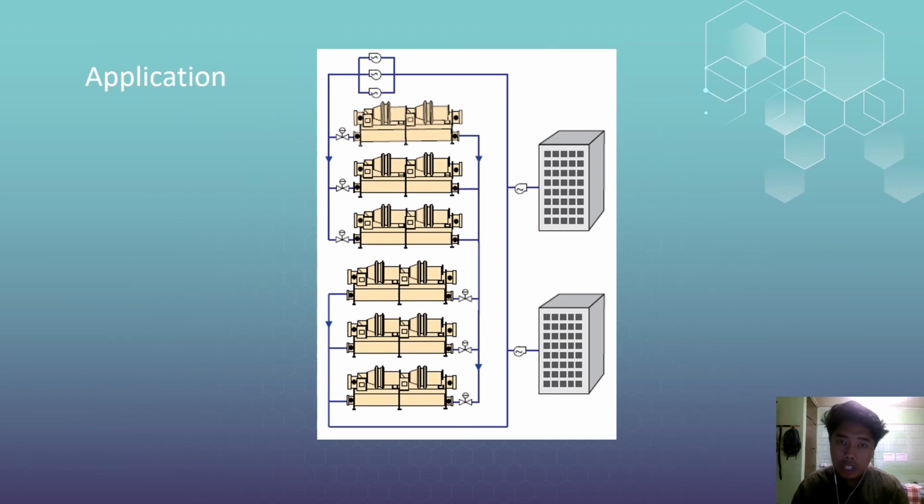Individual chiller unloading characteristics are not as important because operating chillers are more heavily loaded. In addition, practical pipe size limitation starts to affect the maximum size of a chilled water system. As the system gets larger, it becomes more difficult to accommodate the increasing pipe size, both in cost and in space.